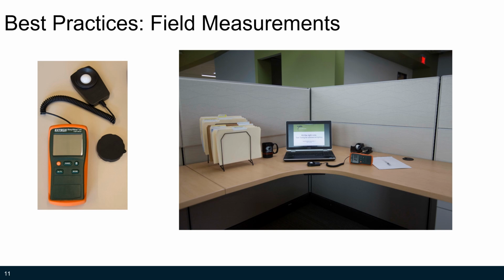The light meter should be placed on the work plane or held away from your body so that you do not cast a shadow on the sensor. It's best to record measurements at a location where tasks will be performed, not in corners of a space and not directly below a light fixture.